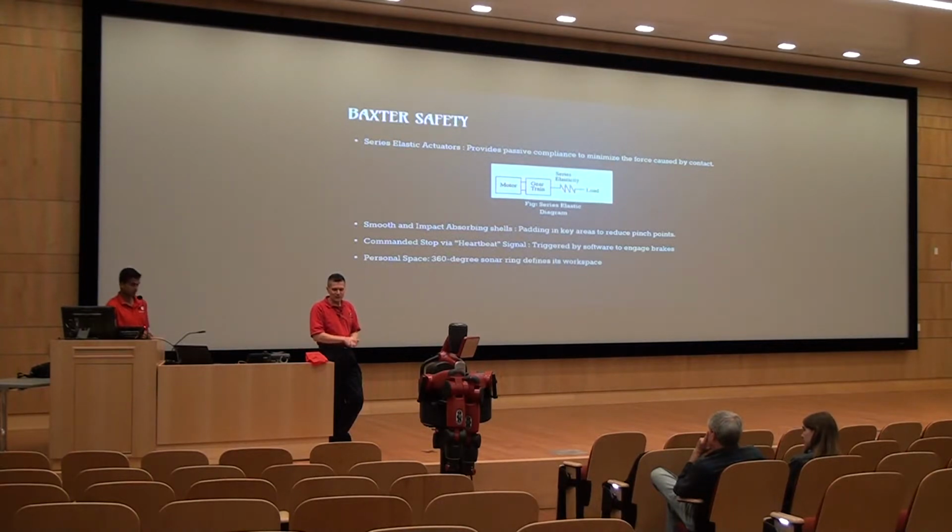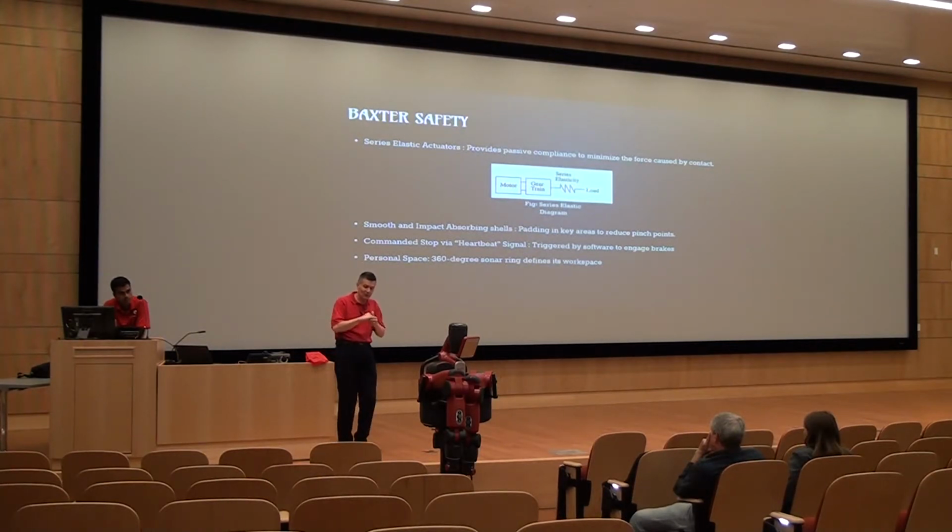Yes. So the standard, which I believe has a 2012 stamp on it, but it was recently enacted last fall, ISO 10218, addresses this in particular. And so there was a technical committee, an ISO TR 5016 or something like that, where they actually looked at the relative forces on each of the axes. If we look at a 7-axis robot, they did an extensive study, and there's still work to do, and I think they'll readily admit that. But basically, what are the thresholds?